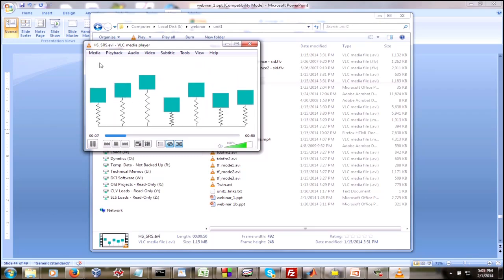And then, as the next step, we're going to plot those as a function of natural frequency for a given Q factor. And once we do that, we're going to have a plot called a shock response spectrum. We're going to cover a shock response spectrum in earnest in an upcoming unit, but for now, I just want you to get a feel for what the basic concept is.